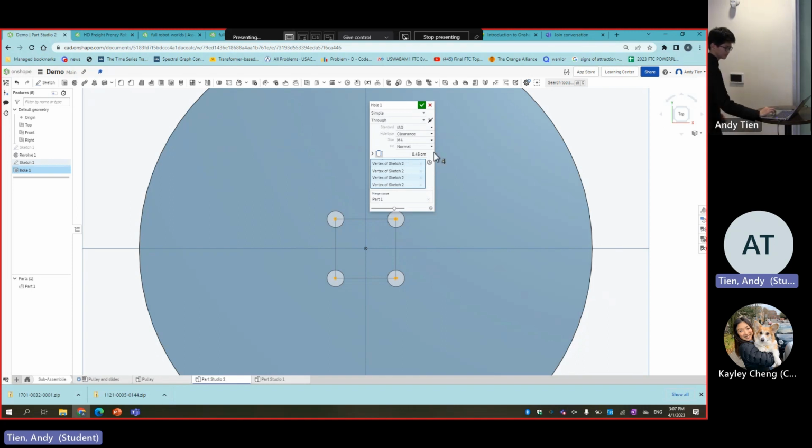And you can see that it's defined as 0.45 rather than 0.4. So why is that? It's because while you're manufacturing the part, the machine isn't perfect, so it has little tolerances. You need to make the hole slightly bigger or slightly smaller depending on how your machine works. That helps you adjust to your machine, and so you don't really have to do post-processing on the part you made. So I'm just going to take a question.